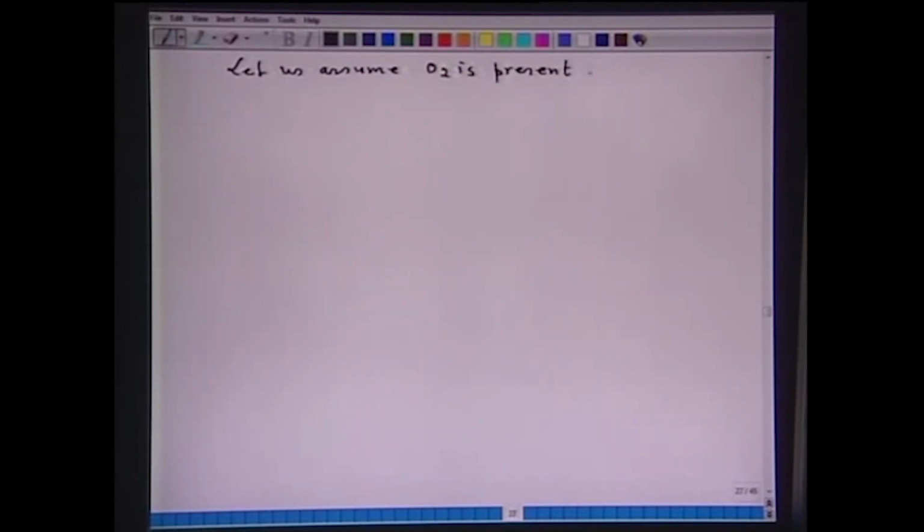Oxygen in DRI is present in the form of FeO. So, we can now calculate the percentage of FeO, which will be equal to (percent iron total minus percent iron metallic) into 72 by 56. Therefore, oxygen